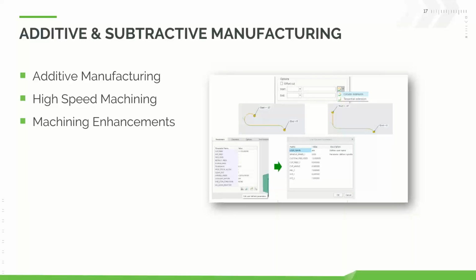A lot of small things, flexibility with particular NC tool paths, getting rid of the limitation of only using predefined CL commands. You can now define your own and define as many different CL commands as you want, and then add them into your tool path. So whatever your post-processor needs might be. Also around that, we added in cutter compensation support. This is within profile passes and high-speed milling roughing. There's actually a customer request to get that cutter compensation added in there. So definitely something that's going to be a welcome enhancement.